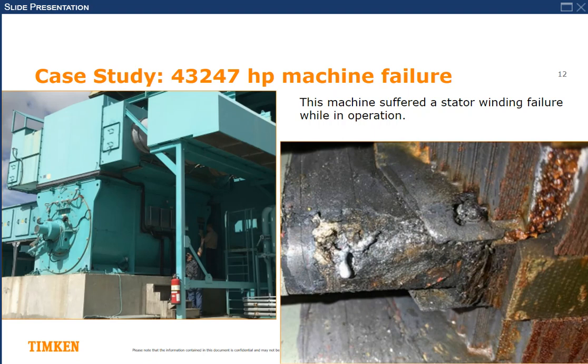The customer had the fan replaced successfully. Unfortunately, there was some debris left inside the machine. So what happened was that some of this debris was flung with the fan into the air circuit, and it hit the stator coil. I've only shown you one coil on the right-hand side, where you can see the point of failure where it actually pierced the insulation. Several of the other coils had similar damage, this was just the point of failure.